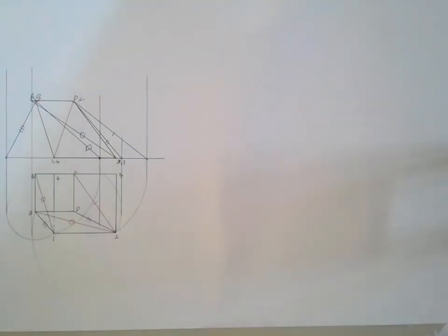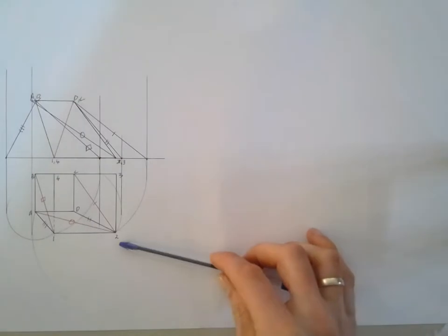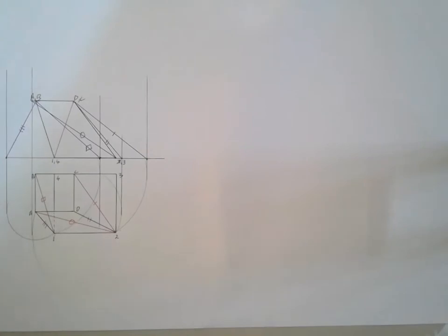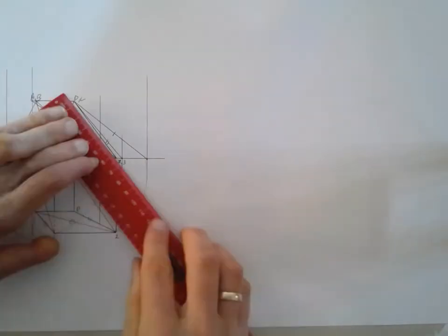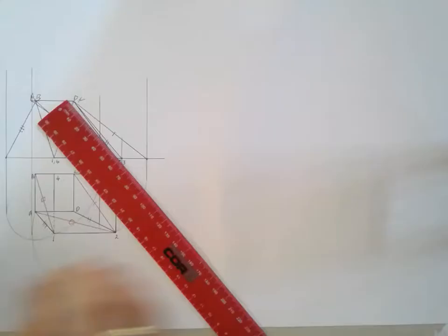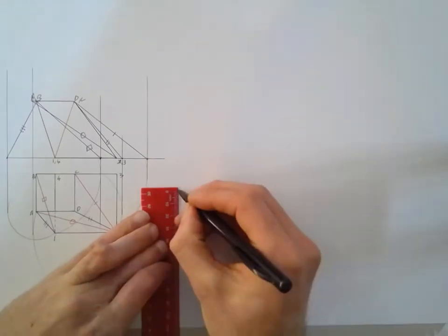Then, because this drawing has not given us a seam, we can go and choose any line that we want to start from. So I'm going to start from the clearest line, which I'm going to take line D2. So I'm going to start with line D2 for my development on the right hand side over here. And I have to go and use the true length of line D2, which is marked with 2 lines there. So go and find my 2-line true length here in my front view, measure that. And that comes out at 59, so I can go and draw a line over here, 59 millimeters in length.